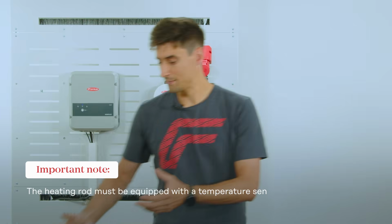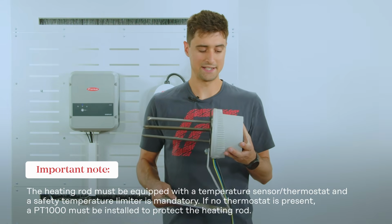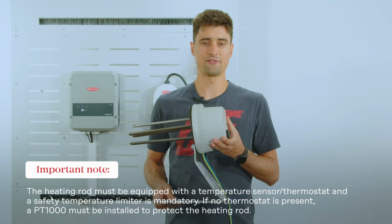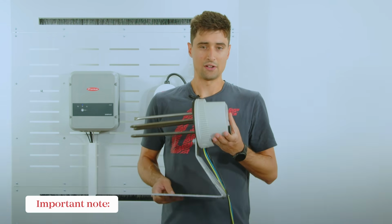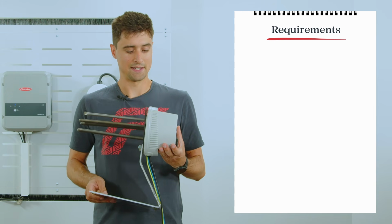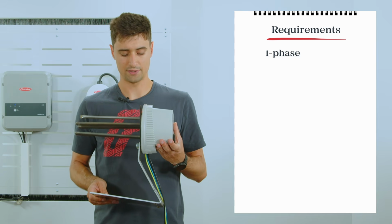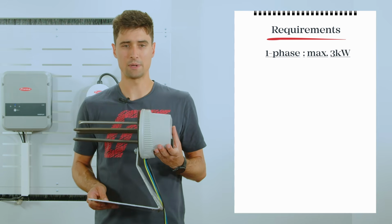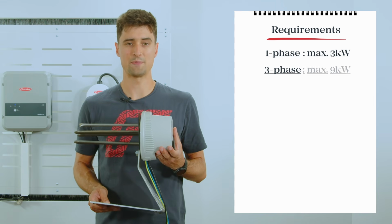Let's start with the heating element. I have such a heating element here, and this has to have certain characteristics so you can use it with the Ohmpilot. First of all, pay attention to the correct power class. If you're using a single phase heating rod, then it must not exceed 3 kilowatt power. If it's a 3-phase heating rod, then maximum 9 kilowatt power.